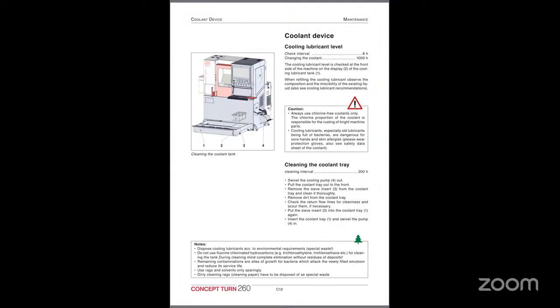So coolant device, coolant tank maintenance: daily check the level of the coolant and also remove the metal chips. If the coolant is dirty, it will produce some bad smell, bacterial growth, and poor surface finish.